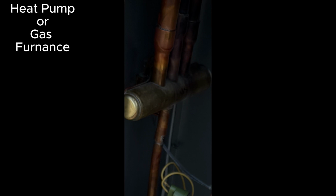And then lastly, you've got something here called a reversing valve. That would be inside the condenser outside. It's got 3 copper pipes on the top and 1 copper pipe on the bottom. So if you just look in your condenser and you see this reversing valve, that means you have a heat pump.